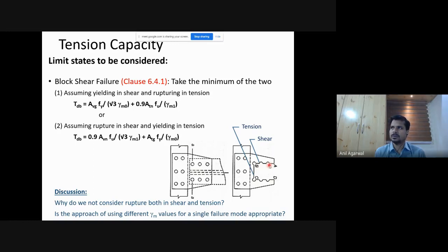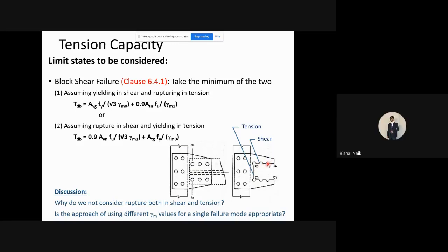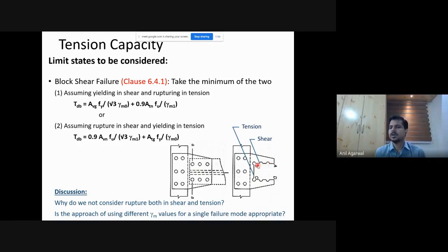Now you keep pulling further, right? Now what will happen is AB will go into strain hardening. After yielding, how many more times the deformation can it take before it ruptures? So at yielding, there is certain 100 times, right? At the time of yielding, you had only one deformation, let's say. Both of them were carrying the same one deformation. This one did not yield for some reason, but this one yielded. Now, it can deform another 100 times before it goes into rupture.